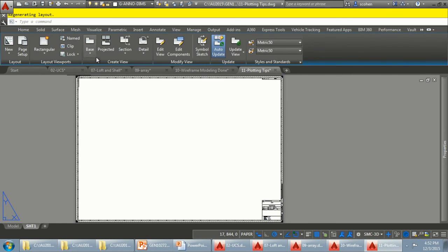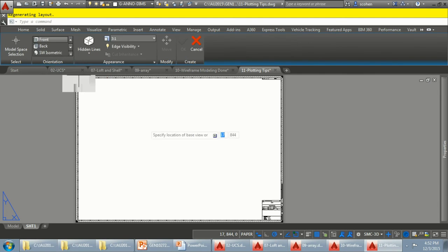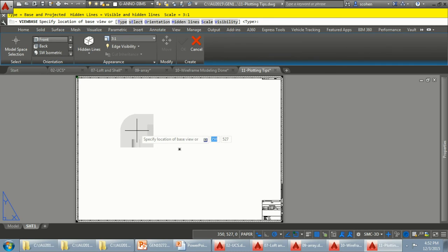And then what you want to do is start with something called a base view. So notice how it says from Inventor or from model space. All right, so I'll pick from model space, and immediately it just basically grabs whatever 3D solids you have in there, okay? Now, if you have different solids, you can actually go into model space and choose which one. In the old version of 2013 and below, it was everything. So you couldn't pick, which it's very nice now you can actually choose.